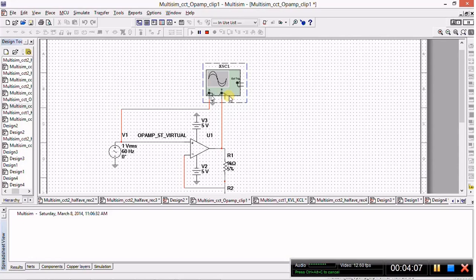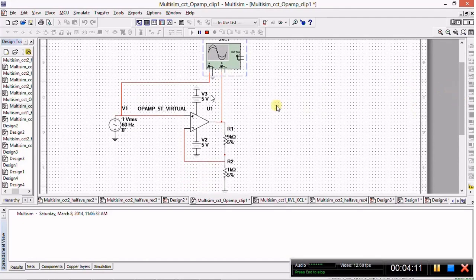This is why we have terminal B connected across the resistance R1, and A connected at the input. Only one of the terminals is grounded, which is A. You could have grounded B instead, because for an oscilloscope, the negative terminals are internally connected. Therefore, grounding one means you grounded the other.